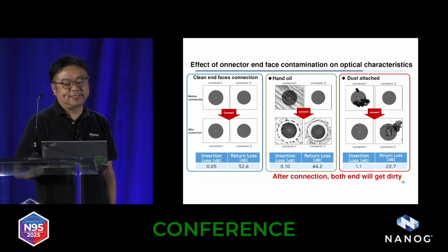As you can see, there is a slight decrease in the optical characteristics. Also, even when connector 2 is clean before connection, the dirt will be transferred after the connection. So make sure both ends are clean before connecting.